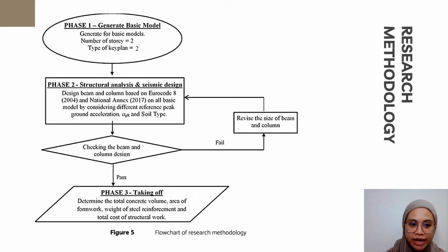This research work is planned to be conducted in three phases as shown in figure 5. Phase 1 is the generation of a basic model without seismic consideration using Tekla Structural Designer software. Phase 2 is structural analysis and seismic design, considering seismic load based on Eurocode 8 and the National Annex with various parameters. The design will be carried out based on different reference peak ground acceleration and soil type. Lastly, phase 3 is taking off, which is the process to compile the total concrete volume, area of formwork, and weight of steel reinforcement. The costing process is also involved in this phase.